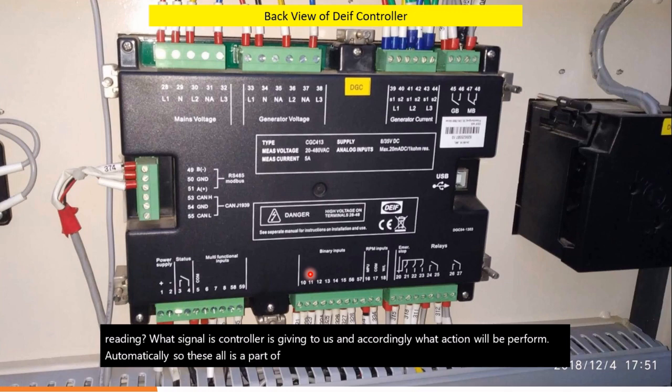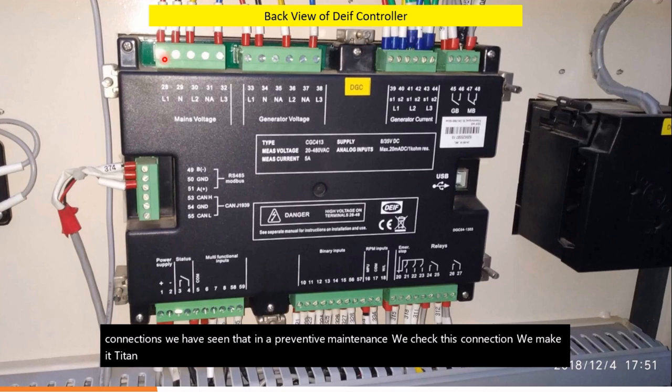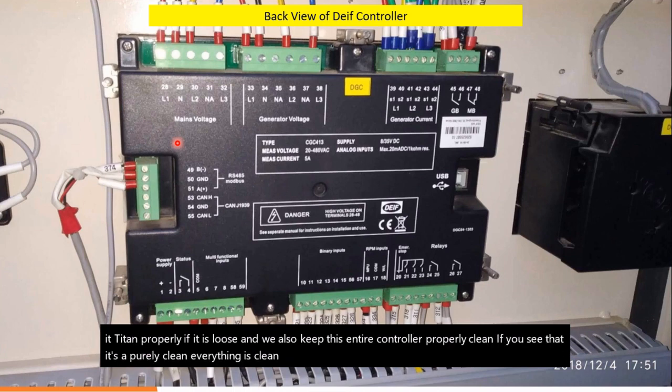But why am I showing you here? Because all these connections, in preventive maintenance, we check, and we tighten them properly if they are loose, and we also keep this entire controller properly clean. If you see, everything is clean here. So in preventive maintenance, one should always ensure that there is no dust deposition.